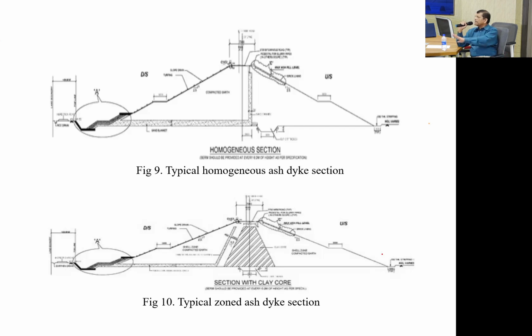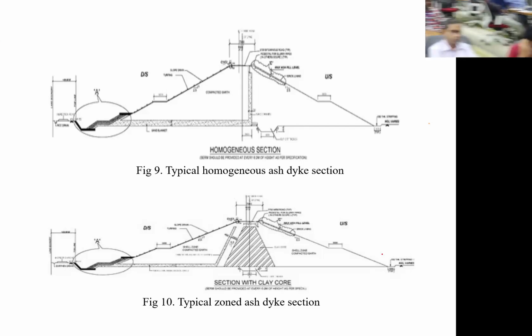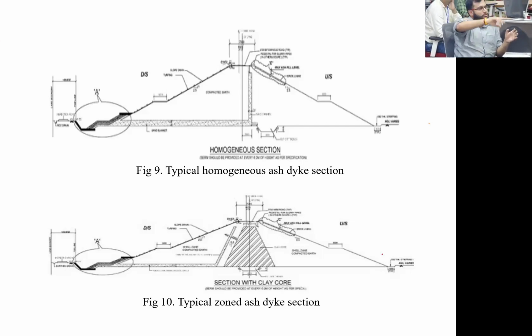On the slope, again, that's why I am saying, when it is steeper than a 3-to-1 slope, we don't have any option. Normally when we put the liner, we go and check it, make sure it is firm to the ground, so we do not have to keep it very loose. But here, it will always be loose because you don't have any option. That's what I am saying. So whether we anchor it or not, we can't keep it exposed to the atmosphere, right?